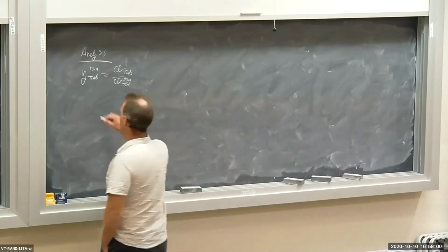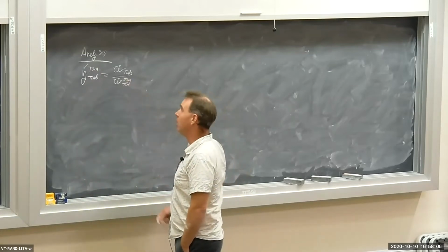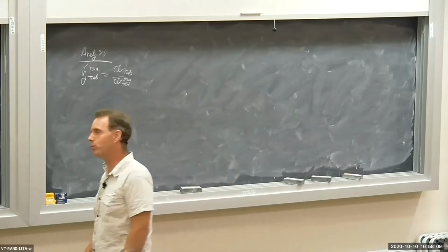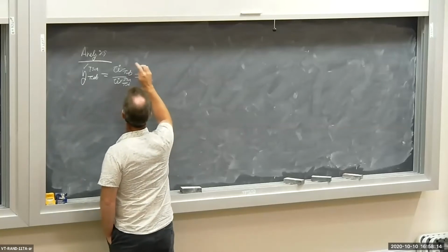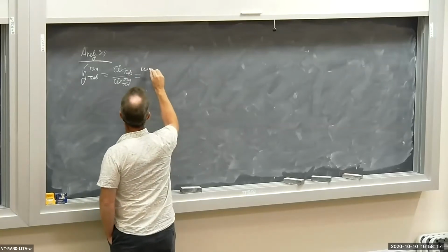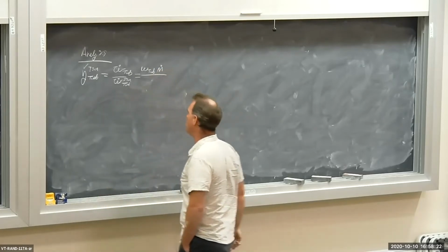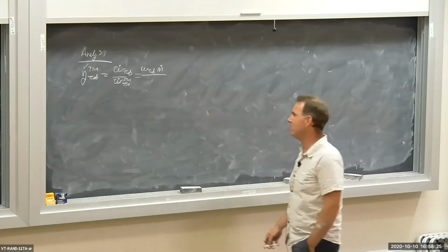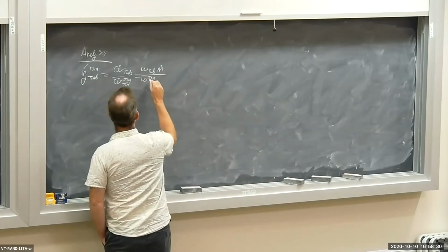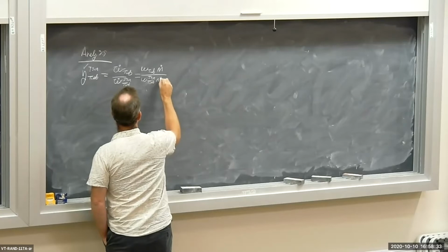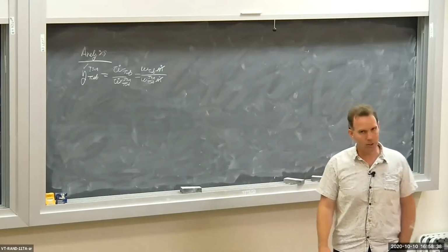Now, I have the isentropic turbine efficiency, it's 86%, and I actually don't want W dot turbine, I want the specific work. Well, okay, I guess we need to massage this a little bit. So W dot turbine is the specific work of the turbine times m dot for the air going through the turbine, divided by W dot for the isentropic turbine times m dot. The m dots cancel out. That's the definition of isentropic efficiency.